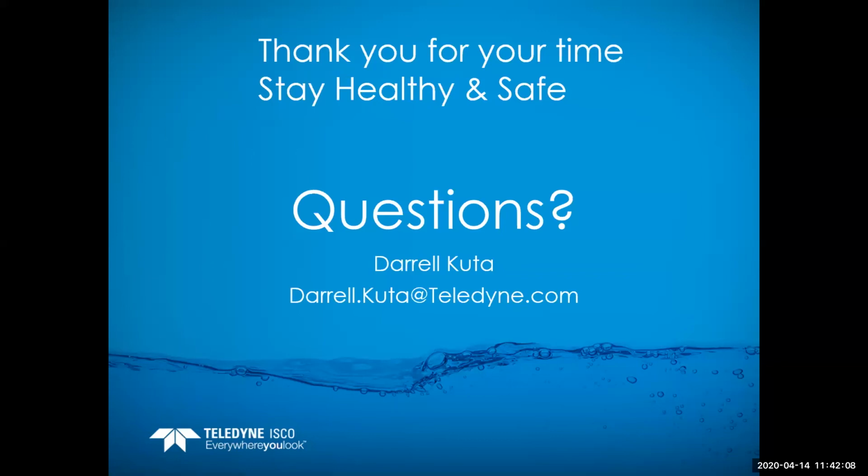It's actually putting out just air. And as far as the non-contact meters, I've seen them work very well even in very cold conditions. The one time I've been aware of problems in really cold conditions was a non-contact sensor outside in a blizzard. There was so much snow going past that it was causing trouble with the ultrasonic, actually blocking the signal to read velocity.